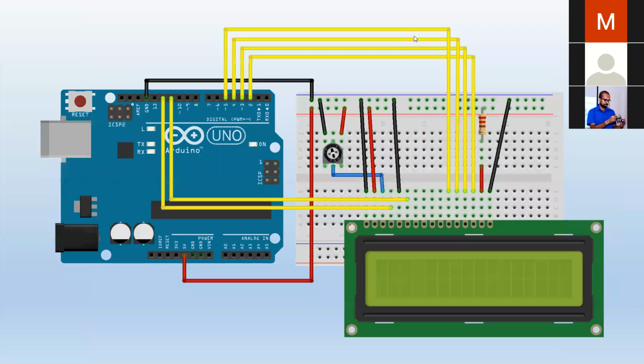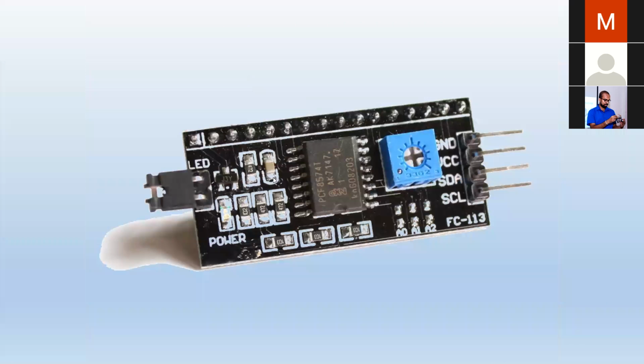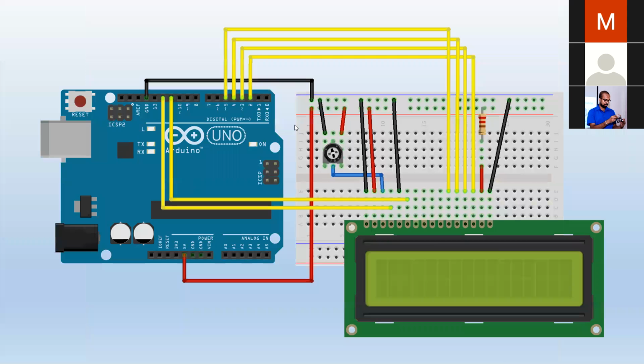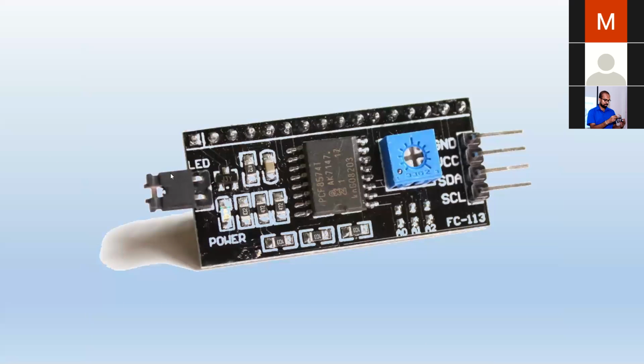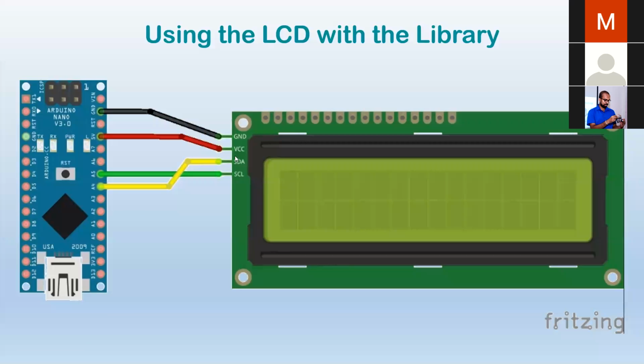This is how you generally connect it, but we use an I2C hat, so it is much easier. To connect an LCD directly, you need all these things, right? You need a potentiometer, resistors, and stuff like that. But when we use this gadget under our LCD, we can just plug it into the I2C line and use it. This is what we call the I2C backpack.